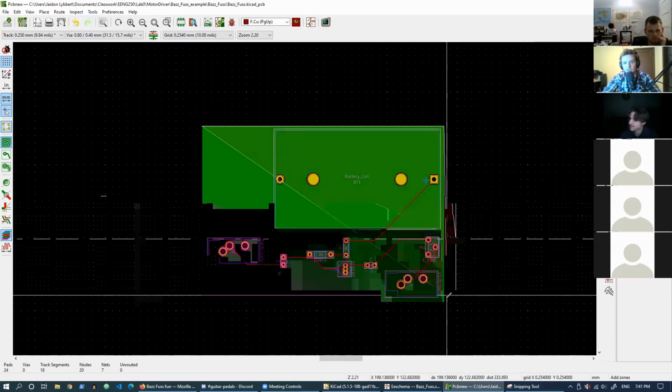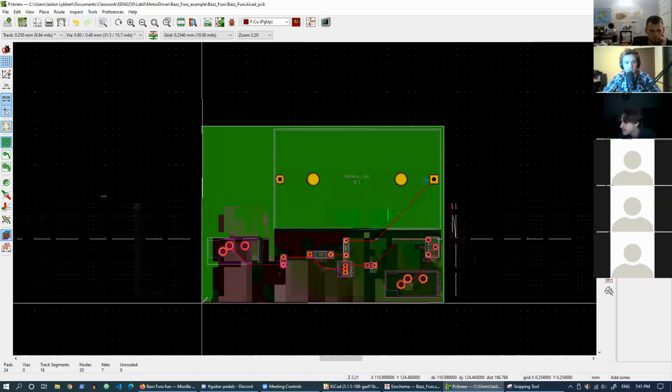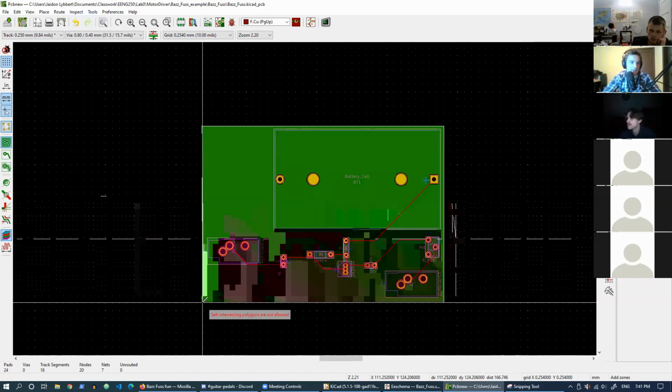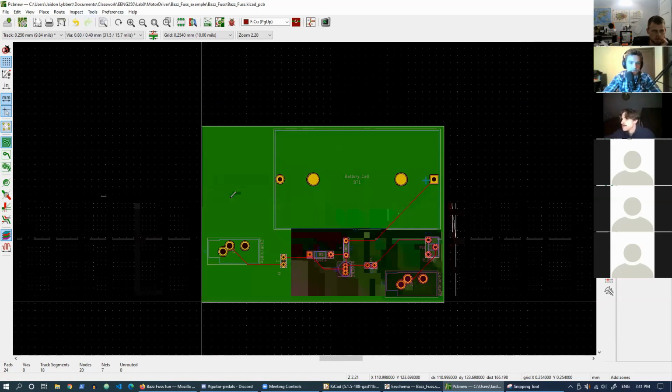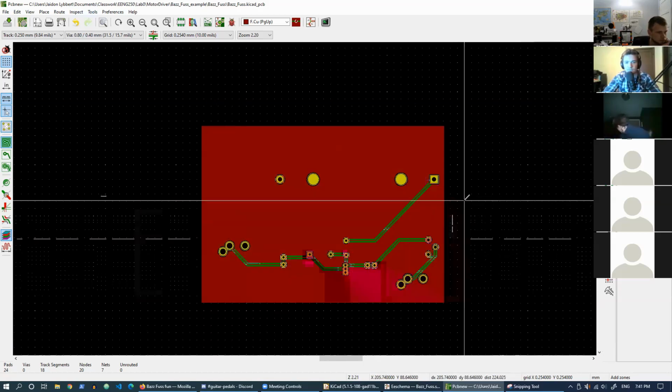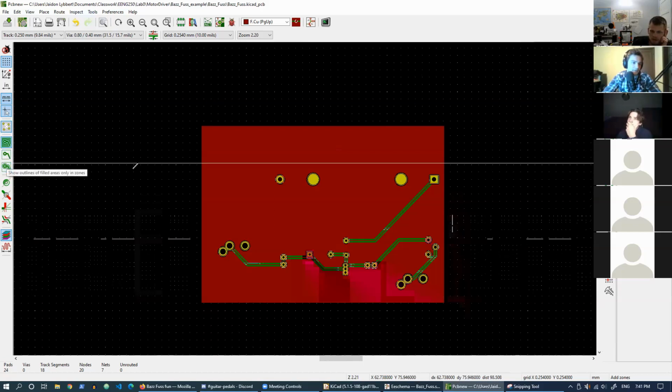And you can also trim the edges. I forget how, but you can just make these ground planes huge and then cut the edges off. Yeah, there's an edge cut tool somewhere. I think it's the filled zones, and you just choose edge cut. Over here somewhere. No, those are just view options. It's on the right hand side.